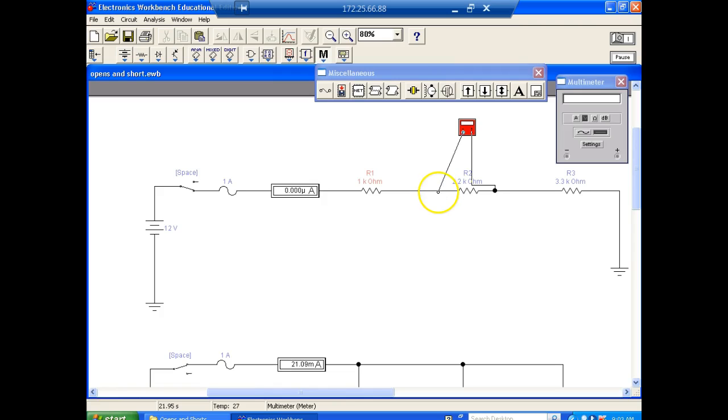It's got infinite resistance, but why is it dropping the voltage? Because there's no current. That's the point. To get voltage drop, V is equal to I times R. If you have no I, you have no V, right? You understand that? So basically if this guy drops no voltage, that's going to take this common and put it right there electrically, right? Your power comes up here, and that's why you measure the full voltage across the open.